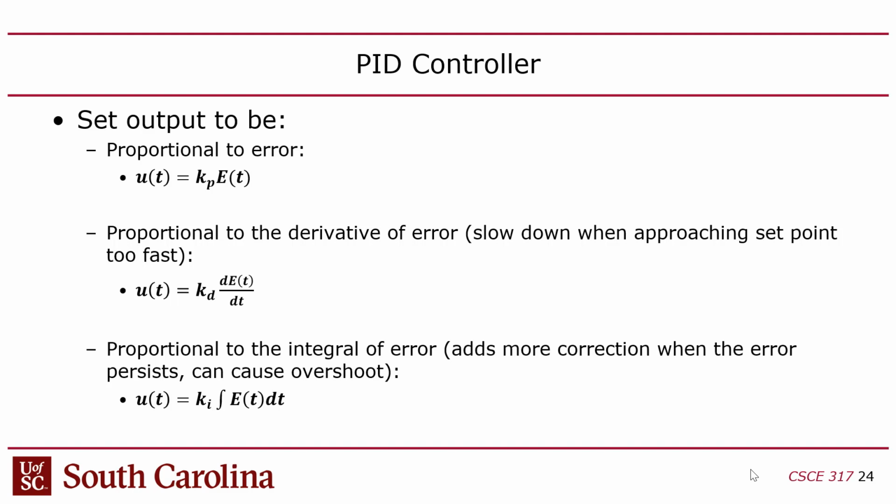You guys, I think you covered this in robotics. So a PID controller is a proportional integral derivative controller. You can have a coefficient that you multiply against the error that's proportional, and that coefficient is K sub P. P is the proportional coefficient, D is the derivative coefficient, and you multiply that by the derivative of the error.